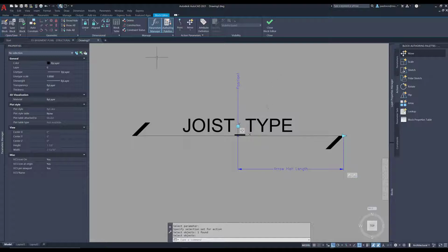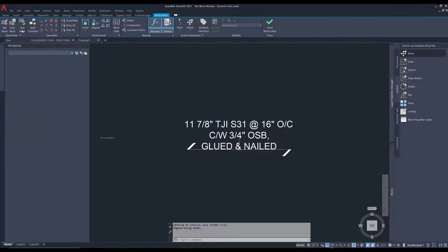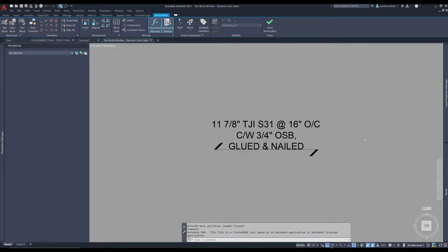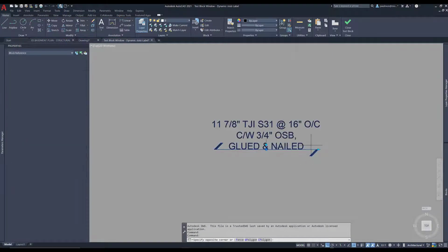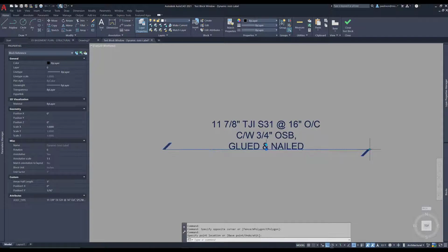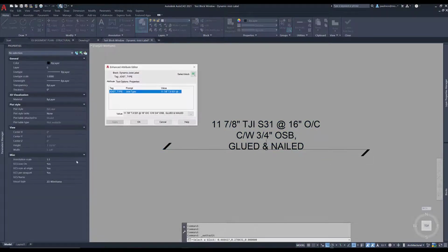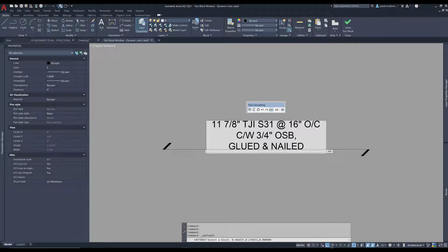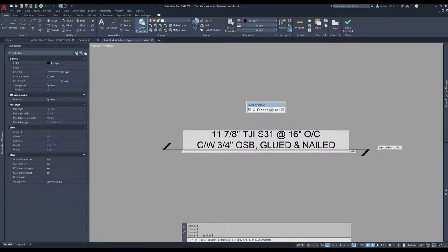So let's test it out. From the test block, again, we can make the arrow a little bit wider and double click on the attribute to remove the line break. So I'm going to put my cursor in here, backspace, and make sure the margin is wide enough to accommodate the line.